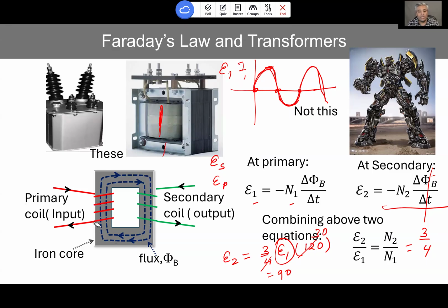They use it to make steam out of water, and then they use that steam to spin the generator wheel. So in that source where the electricity is being generated, the voltage produced is not that high. But when we want to transfer it to the place where it's being consumed over a long distance, we want to transfer a lot of power, and voltage is low, so power is the product of current and voltage.